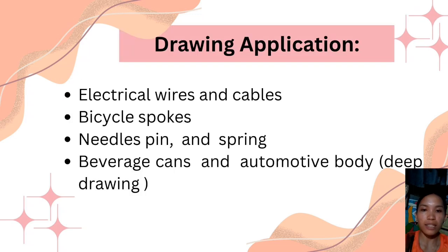Then the last part is the drawing applications. Under the drawing applications, there are also four applications. First we have electrical wires and cables. Next is bicycle spokes. Then third is needles, pins, and springs. Then last is beverage cans and automotive bodies, or deep drawing.